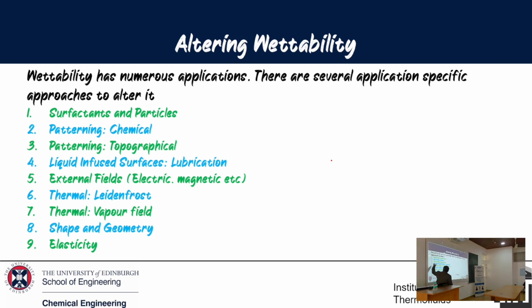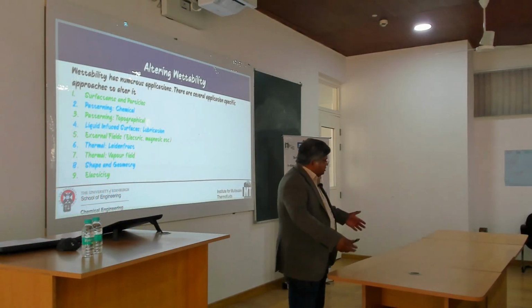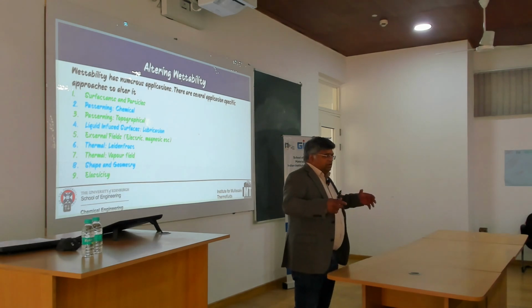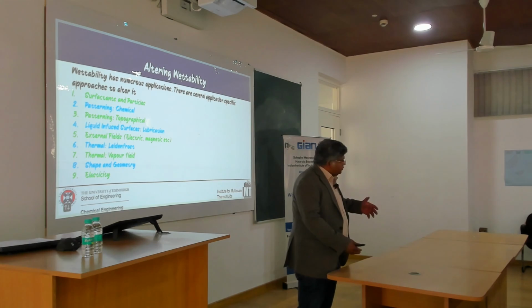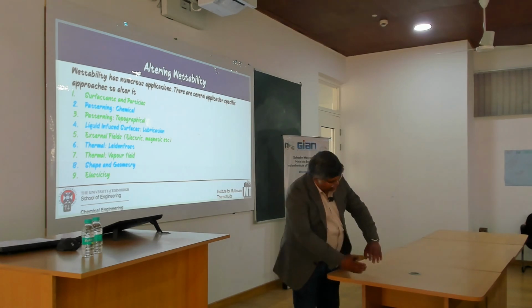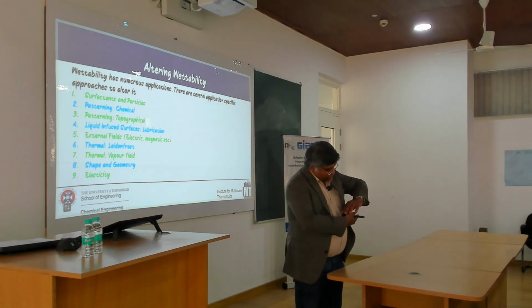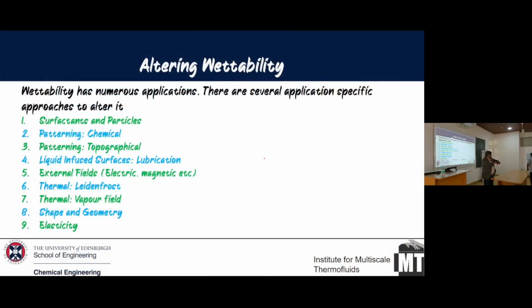Most recently, people are using liquid-infused surfaces. So you've got these surfaces which are solids, but you've got these pillars where they inject fluid. Usually they put some sort of an oil. Essentially, when you deposit an aqueous droplet, the oil will repel the aqueous droplet, so it's going to sit on the film, but then it's also going to climb on the aqueous droplet.